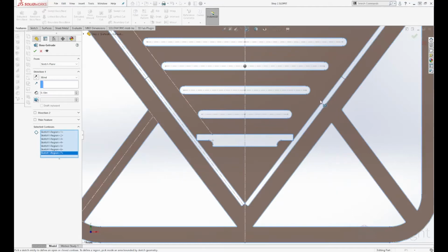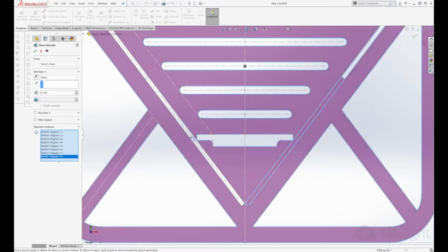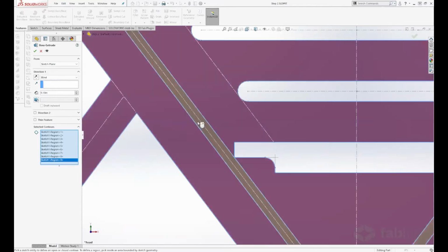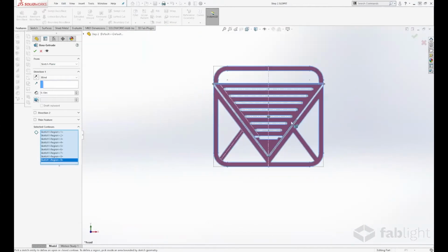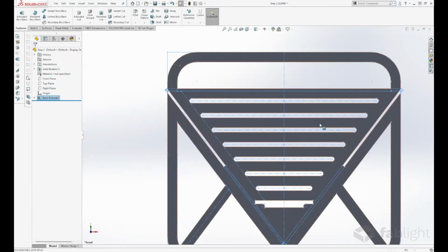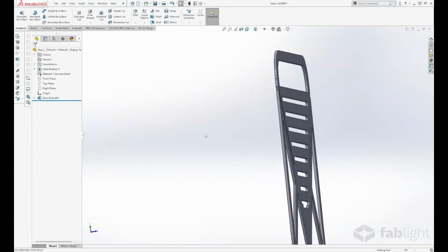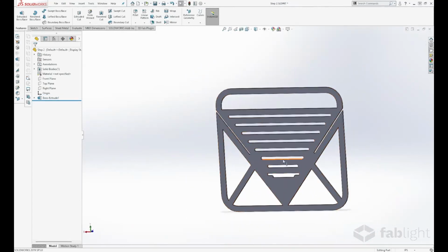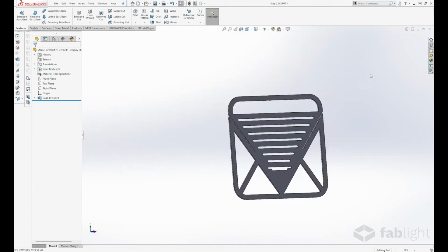Now, we've got to remember these last two parts because these are pretty important. So remember that center line that I created here. We're actually going to come back and use that center line to split that sidewall that we made. And we're going to select these regions down here because we want this to meet in the middle of these two materials when we create these parts, right? And then we're going to extrude this by about 1/8 of an inch. Okay, so there we are. This is our first part. You can start to see it come alive, start to see what we're actually going for.